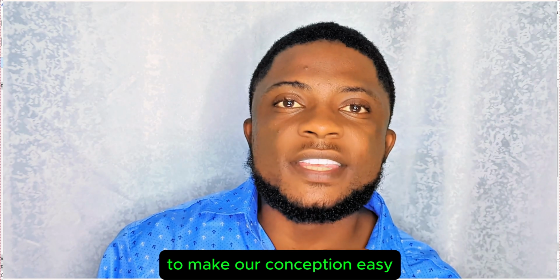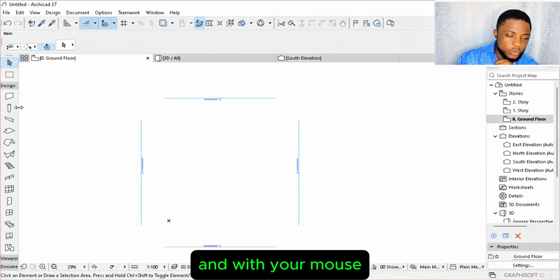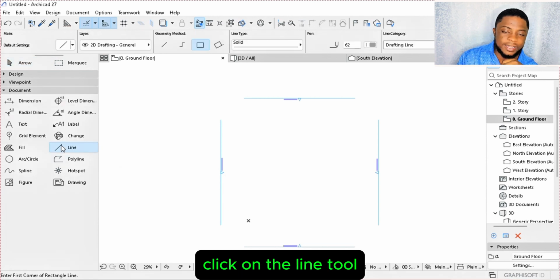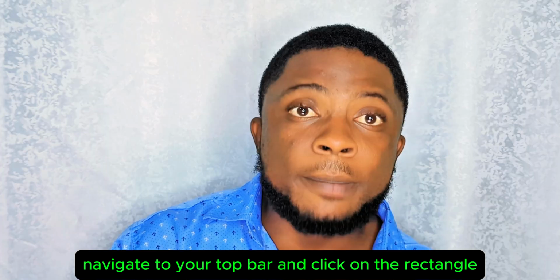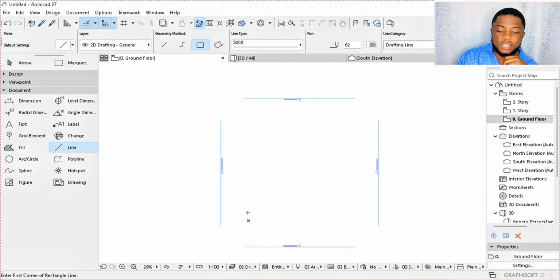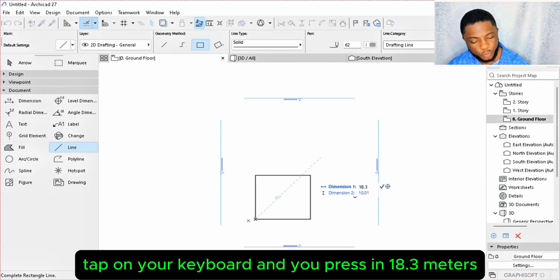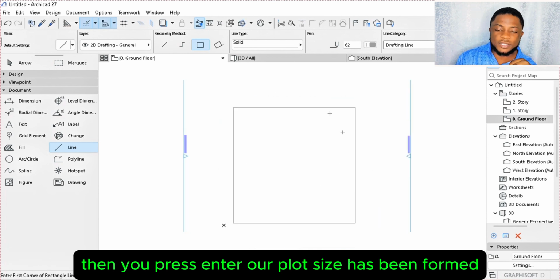To make our conception easy, we are going to set our grid lines. So navigate to the right part of your screen and with your mouse try to drag this out so we see it visible. Close the design tab and move down to documents. Click on the line tool, navigate to your top bar and click on the rectangle. The plot size we'll use for this project is 18.3 meters by 18.3 meters. Nice. So you're just going to click anywhere on the screen and type in 18.3 meters. Then you tap on your keyboard and you press in 18.3 meters. Then you press enter. Our plot size has been formed.